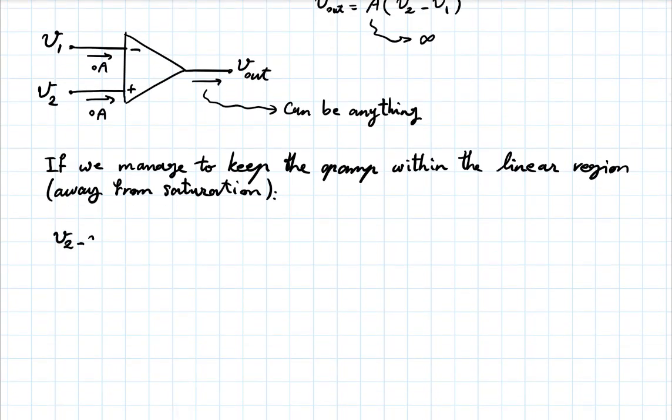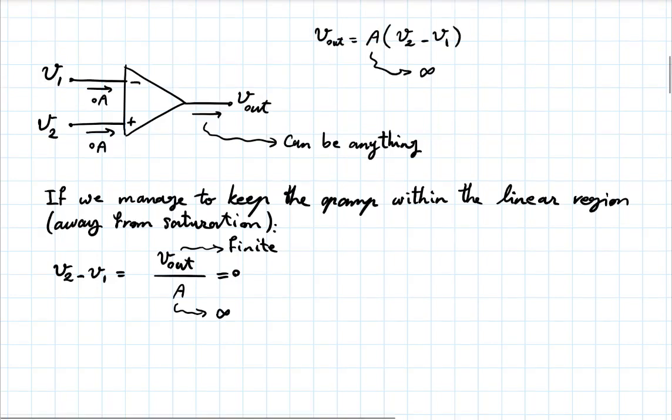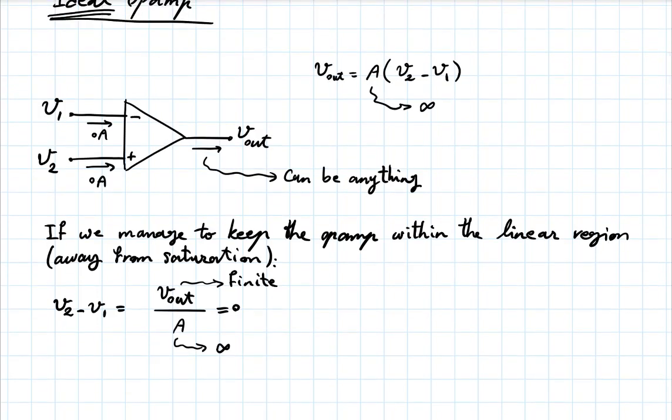So you can conclude that the difference between these two inputs is 0. And so whatever voltage you see on one of those two inputs will be replicated on the other input, without the two being physically connected. In fact, inside the op-amp, there's an open circuit there, right? They're not connected internally. That's very important to keep in mind.